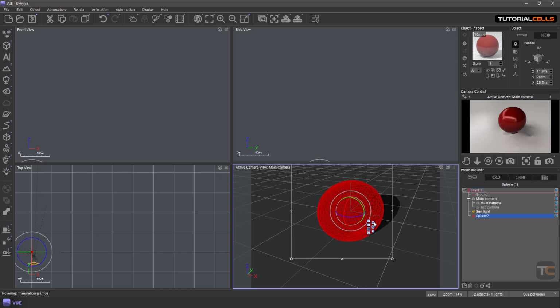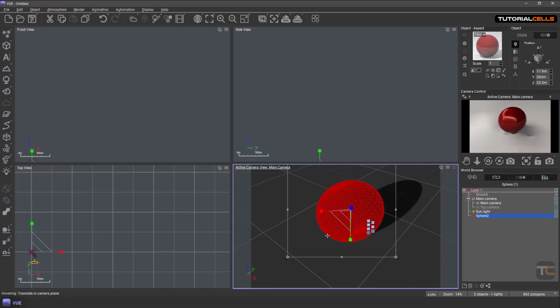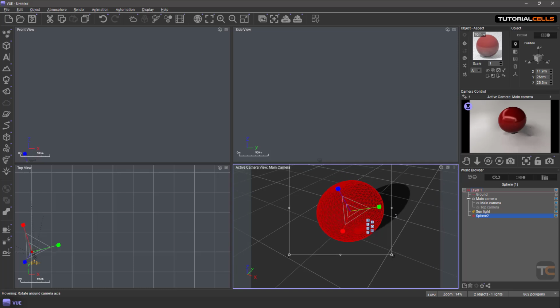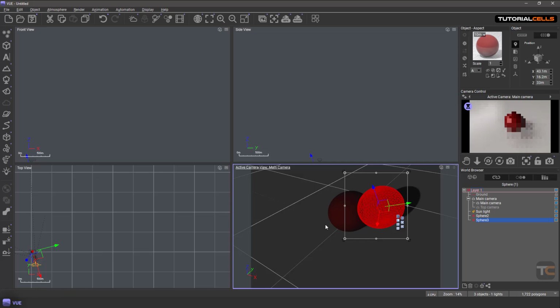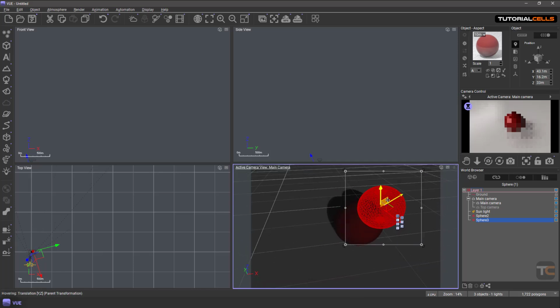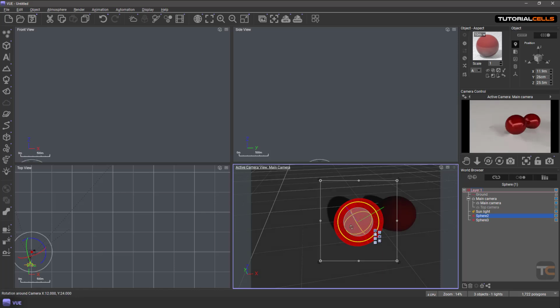So if you change to this, it's better to see that. Look at this. It's parent and it is view. If you take view, the Z-axis is always pointing to your camera. If you set to parent, for copying an object, you can press Control C and Control V, or you can pick one of these handles and hold Alt, and now we are copying. So you can see we have two objects. This object is in this direction and this object is in, for example, this direction.